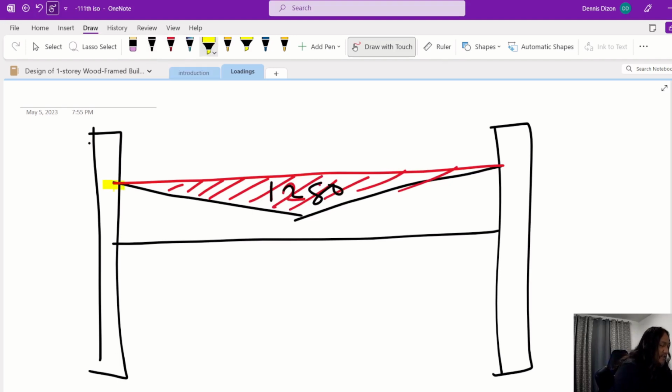And then the bottom of the scupper is flush with the top of the roof. But like I said in the code, you have to consider an extra 30 millimeter height for the surface tension before the water starts to flow out of the scupper. So you still have extra 30 millimeter water that you should consider.